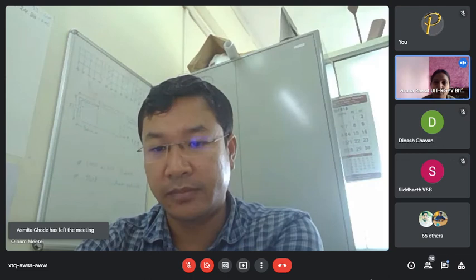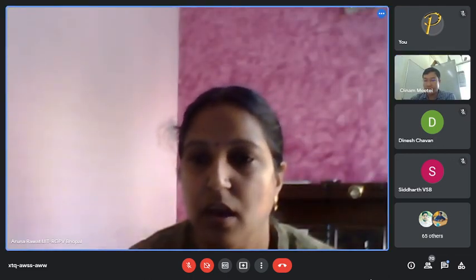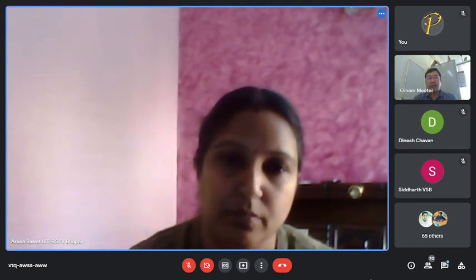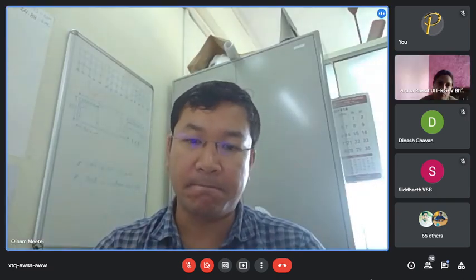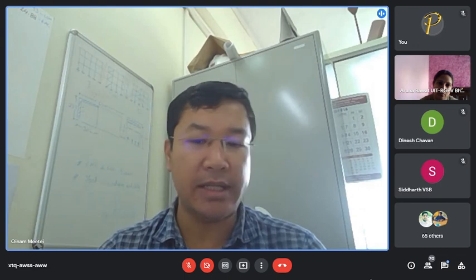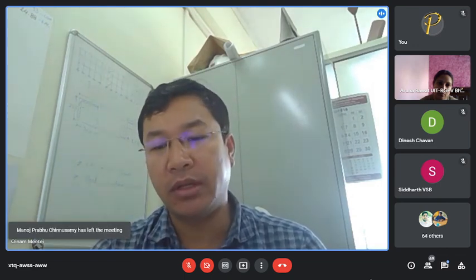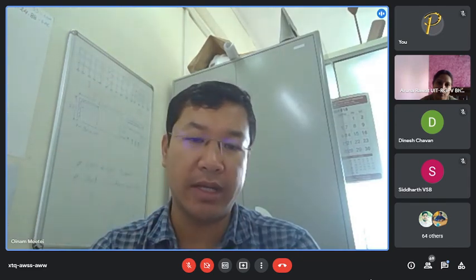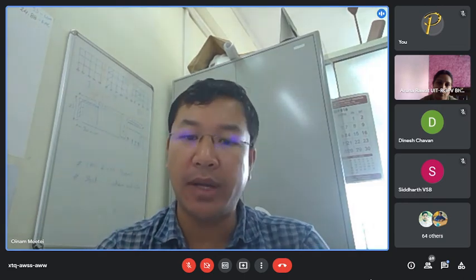One more question. While defining the plastic hinges in SAP2000, how much distance do we need to take from the end of the column and the beam? If you look in the literature, you'll find countless plastic hinge length calculation formulas. One very standard formula is by Park and Paulay.